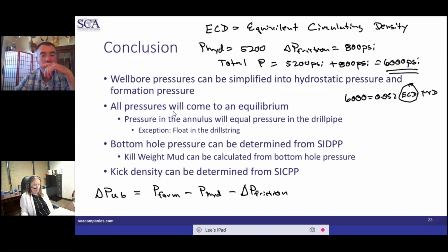When do you use managed pressure drilling? That's a great question. When you use managed pressure drilling is when you can't get away with regular drilling. So if you have really tight windows, meaning your ECDs are approaching your shoe fracture pressure or injection pressure, whatever you want to call it. We generally call it fracture pressure or leak off test pressure. If those ECDs are starting to get really tight to that, then MPD becomes an option.